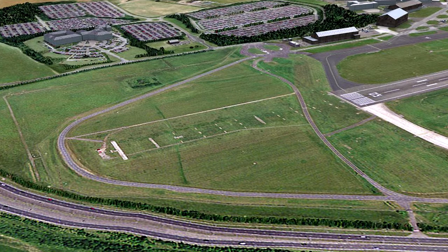The second of the specific distances that a pilot needs to understand is the takeoff distance available, normally abbreviated to TODA. The takeoff distance available is that distance from the point on the runway at which the aeroplane can commence its takeoff run to the nearest obstacle in the direction of takeoff, projecting above the surface of the aerodrome and capable of affecting the safety of the aeroplane.